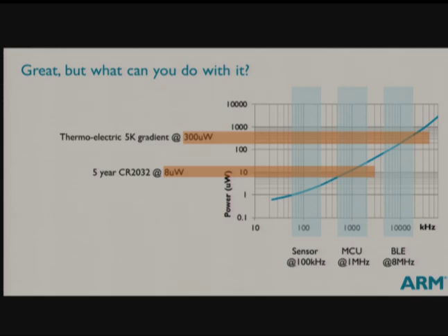So you might ask, well, yeah, but I don't need a megahertz all the time. My duty cycle's probably, 10 to 1? What would happen if I do that? I'm going to get 50 years out of it. That's great. I can install it and build it and forget about it. And of course, the answer is, no, you can't. Because the self-discharge time of a coin cell is about 10 years. So at a 10 to 1 ratio of that 1 meg microprocessor, you actually get about 9 years. And that's the best you can do because the battery's going to be flat in 10 if you do nothing at all. So building battery systems, again, it's a system problem, stupid.